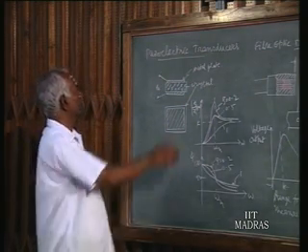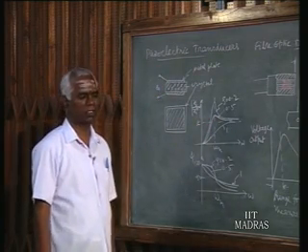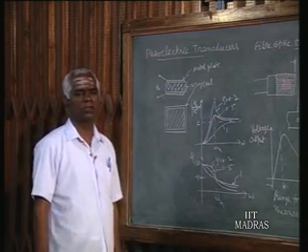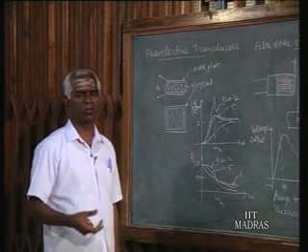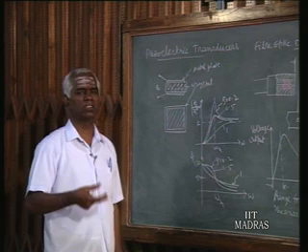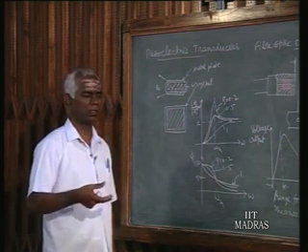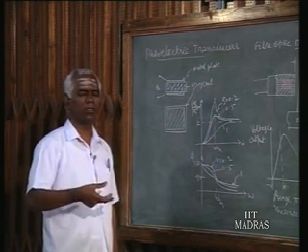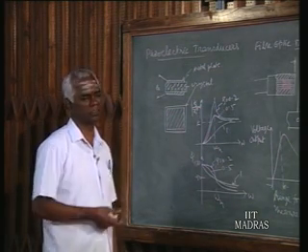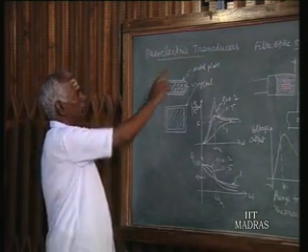Now regarding piezoelectric transducers, we know that there are natural crystals which, when we give vibrations or displacement, produce a charge or voltage. Similarly, it is a reversible action: if you give an AC voltage at the same frequency, it vibrates. This is the property made use of in piezoelectric transducers.